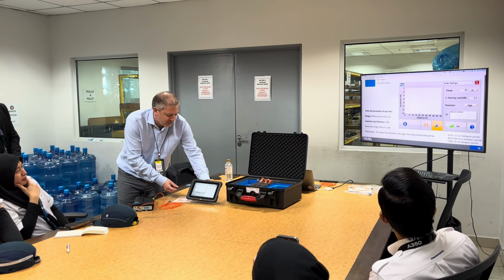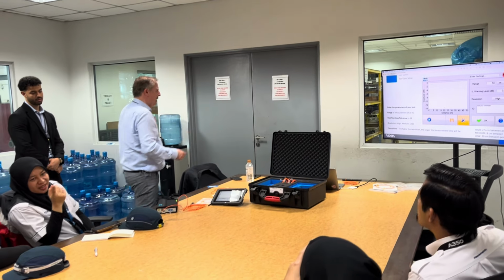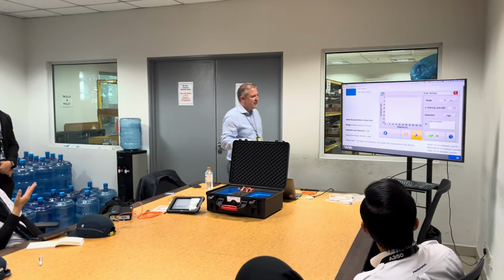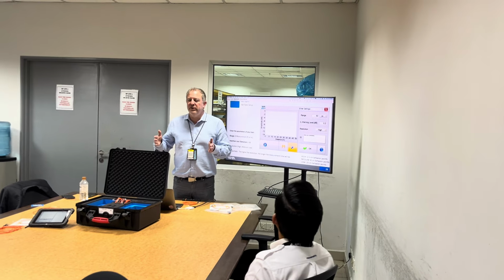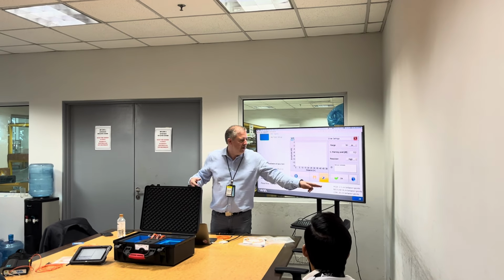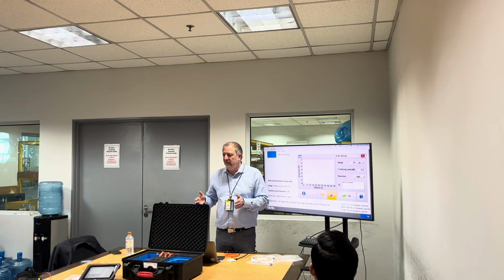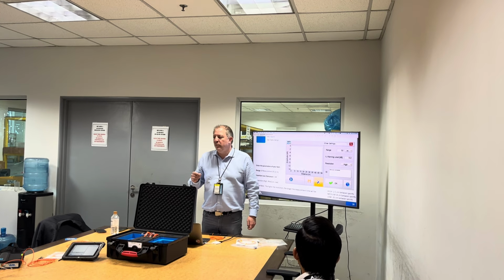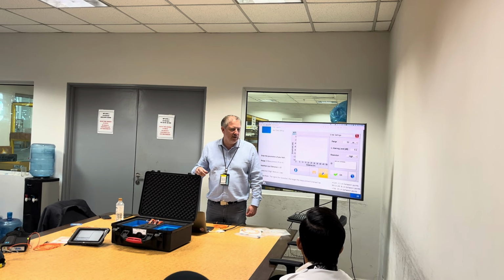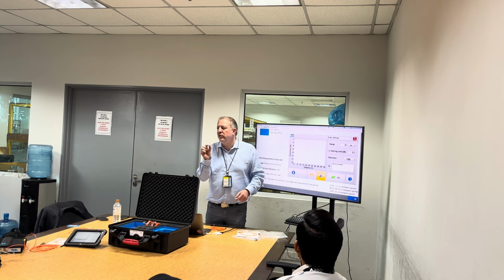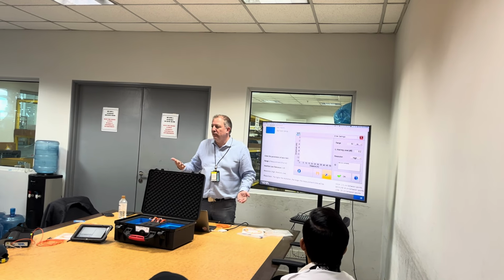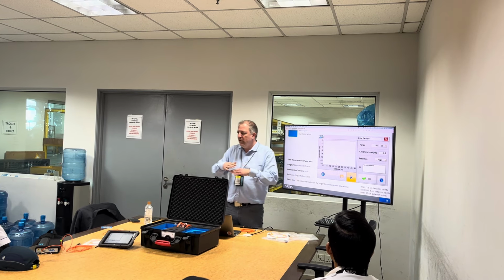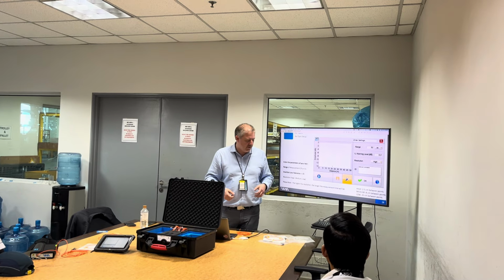Just so you know, before I launch the test, I can give you some additional information. The low resolution is going to be 1 point every 20 centimeters. Medium is going to be 1 point every 8 centimeters. And high is going to be 1 point every inch, every 2.5 centimeters. So this is very high resolution. You know exactly where the issue is, and that's the best for accuracy when you do measurements. But please start with medium or low first, just to have a quick scan, and then you can run the other test after.